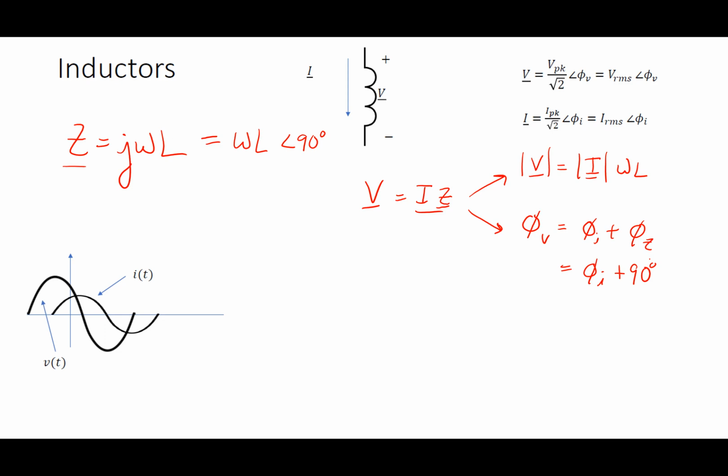Okay, if I drew the phasor diagram here, what would I write? Let's start with the voltage. Where is the voltage? It would actually be in the first quadrant in terms of the phasor, because if it is peaking before t equals 0, this would be cosine omega t plus something. So I know you have to have a positive angle. Where would I of t be? He would be over here in the fourth quadrant. But will you add?